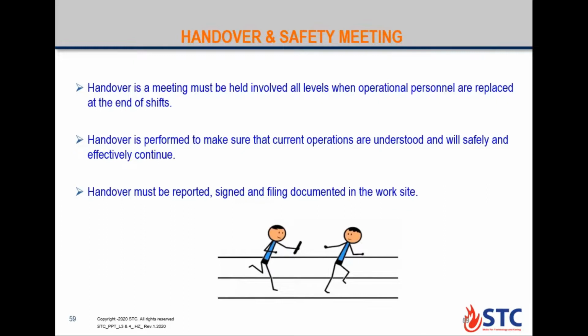Usually the handover is performed to make sure that the current operation is understood and will safely and effectively continue. The best way is a written handover, not verbal information or instruction. It must be written, with each point discussed with the other shift, in the same place.